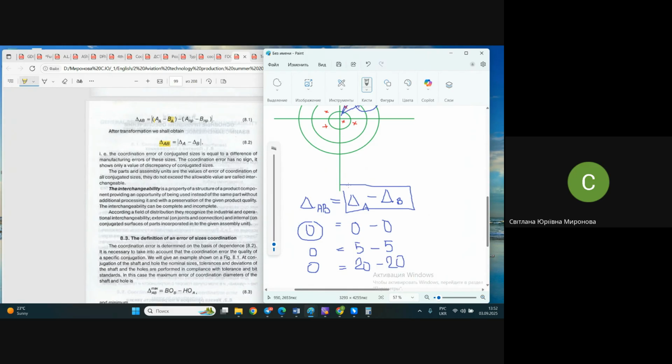On one hand, we may talk about interchangeability. What is interchangeability? The property of an object that shows this object is usable instead of another object without additional work, without adjustment of sizes, without changing of volume or some other properties, in the most general meaning. When we're talking about interchangeability of structural components, mostly we talk about their geometrical interchangeability.